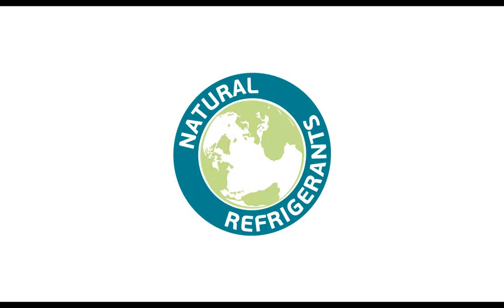In the testing that Embraco has performed to date on HC refrigerants, what is the efficiency difference for R600 and R290 as compared to R134A in equivalent systems? Yeah, we only touched on R290 versus 134A and 404A. R290 versus 404A should be about a 15% improvement. 134A to R290, you should see 20 to 30%. R600 is actually a more efficient gas than R290, so those numbers would go up a few percent from R290 to R600.